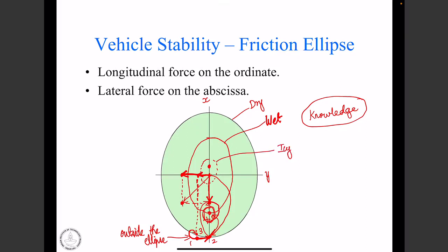Yes, absolutely. That's why if you drive a car on an icy road, even if you touch the brake a little bit, the wheels may lock, correct? That is because our hydraulic brake system, assuming that we are driving a car, is designed to provide this much braking force when the driver completely depresses the brake pedal, right? On the other hand, let us say this limit corresponds to 20% of the pedal displacement, and we are already outside the dynamic limit that can be supported. So that is why the wheel locks on an icy road.